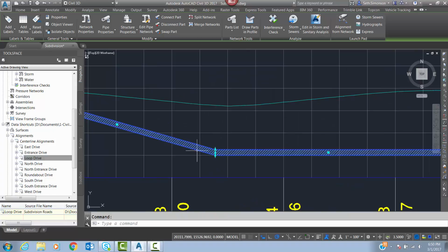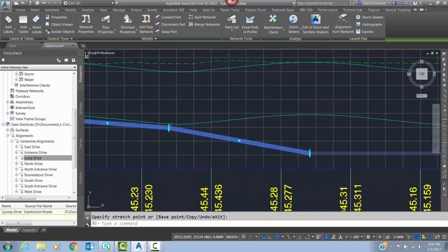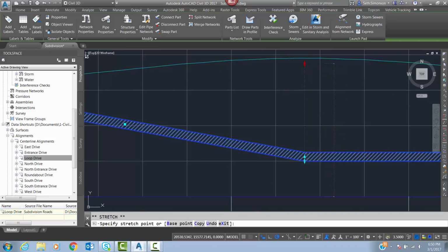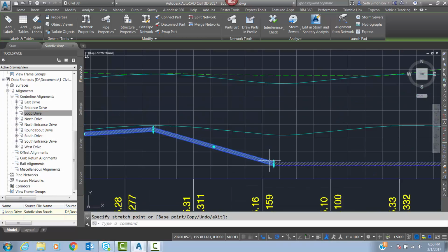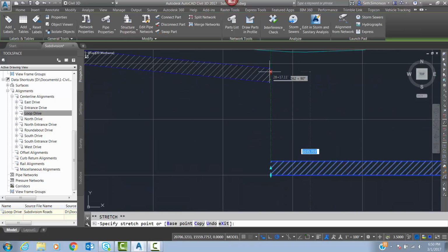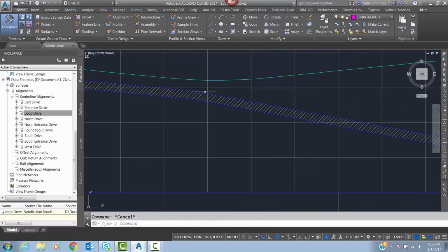Now, by selecting both the coming-in pipe and the going-out pipe, if I grab the grip, I'm bringing both of them up together. So I'd select that pipe, grab the grip, and move that up, maintaining that the top of my pipe is still below that surface. Okay, go back up. Oops. See there, I didn't select my next pipe. In that situation, I just grab this grip and make sure I snap to that end point so that I'm maintaining that it's not separated.